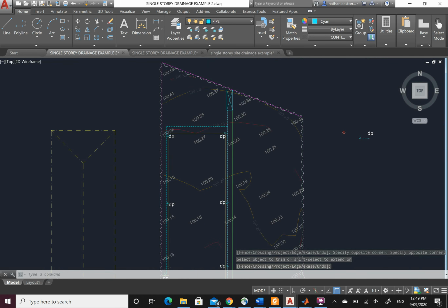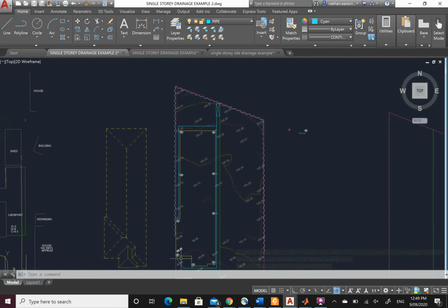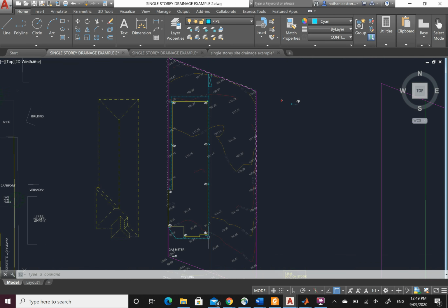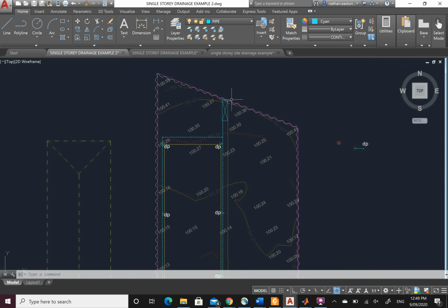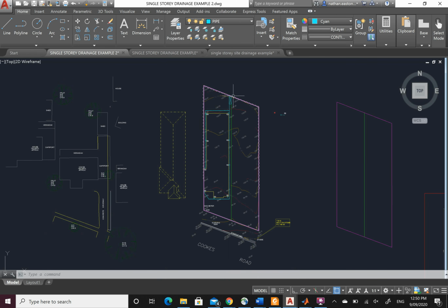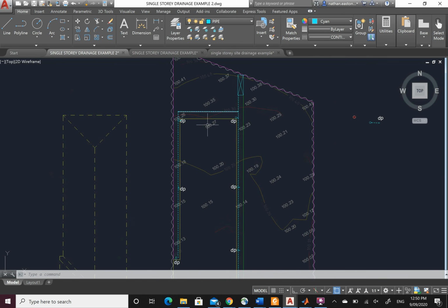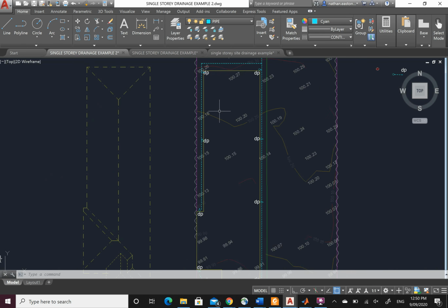Cool. So what's happening is the downpipes are going to connect to the pipework underneath the ground. They're then going to go to the tank. So this tank here, the rainwater tank, will be used for irrigation. So they'll use it for the water in the backyard. They'll also use it for the toilets. So they'll connect this to the toilets, so you're not using mains water to flush.